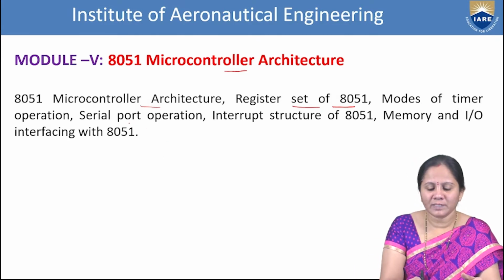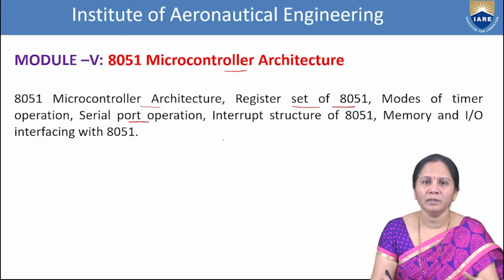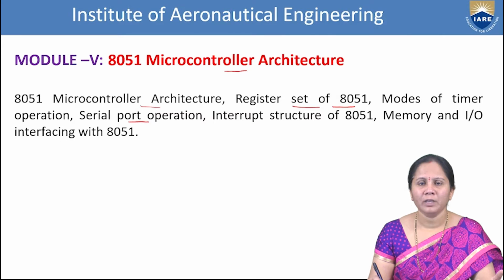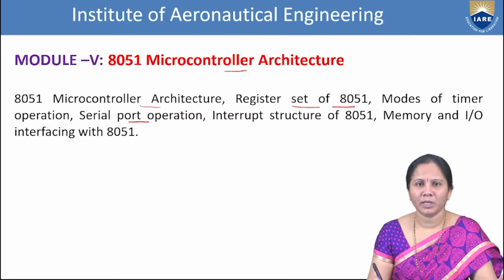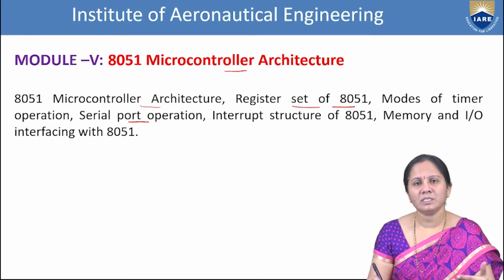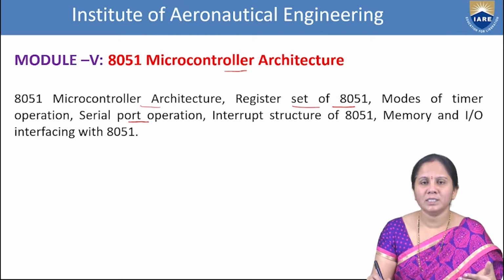Next we saw the serial port operation. In this, we discussed how to set the baud rate and how to perform serial communication by using UART. We discussed the registers involved in serial port operation, like SCON and SBUF.